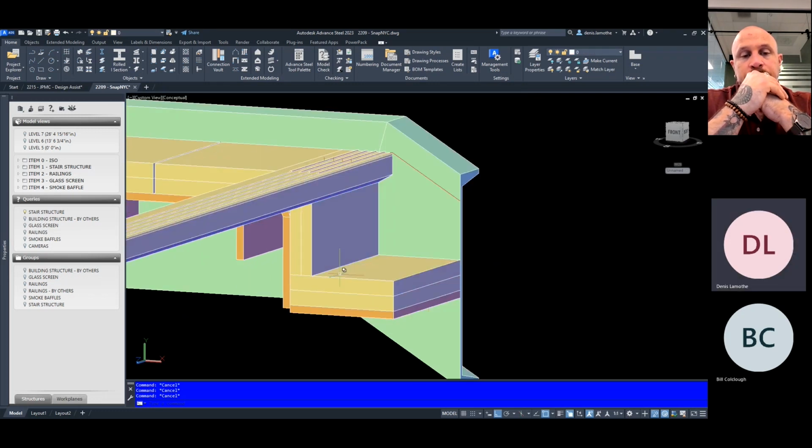It's a little uncommon to have exposed steel, maybe on the riser, but not in the treads. It tends to be more of a slippery material. If we use something like painted steel, which I don't think we have, but if we ever do, it would typically have some kind of grit, like sand applied to it, or silicone beads or something that would give it a rough texture. Again, that prevents people from slipping on it should there be any water or anything that would make the stair otherwise slippery. So a painted finish is not really something that we work with very often for tread finishes.